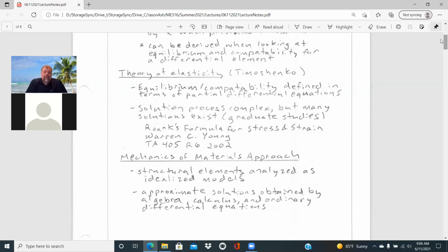But I think from that standpoint, that's a good resource if you're dealing with kind of a common type problem and you want a theory of elasticity solution. You may find that in general form in Roark's textbook there. And those are all set up in terms of relationships with respect to variables so that you can put your geometry variables, your material properties, and all that stuff in there to determine what displacements might be, what the state of stress might be.